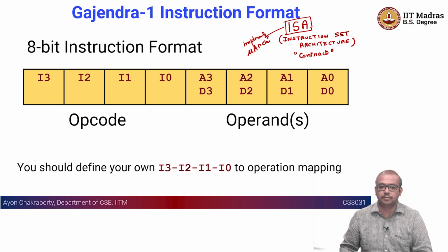So before that, you need to understand what kind of necessities or applications are going to be running on your CPU and what their demand is. What kind of operations do they do? Do they do a lot of floating point multiplication, or are they mostly going to do integer operations, or are they going to do any mathematical computation at all? Maybe there are a lot of data transfer operations. So depending on that, you might be inspired to make your ISA flexible towards a certain class of applications.